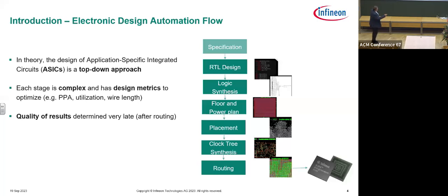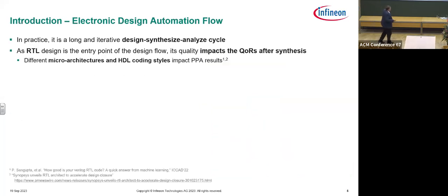I'm addressing more here this area, RTL design and logic synthesis, but even there, if we don't know the clock tree synthesis, if we don't know placement, if we don't know the optimization, it's hard to know if my Verilog code is good enough or not. So therefore, we want to try to get information early in the design process.